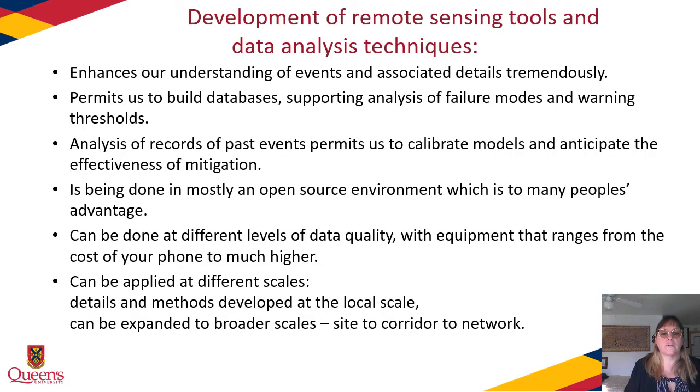Overall conclusions for this talk and related to the development of these data analysis and remote sensing tools are that they enhance our understanding of events and the associated details a great deal, permitting us to build databases, and that lets us calibrate the types of models you've seen and also helps us try to identify warning thresholds related to failure modes. We work with past events, moving towards forecasting when we are able to calibrate these models, and in particular this permits us to anticipate the effectiveness of mitigation.